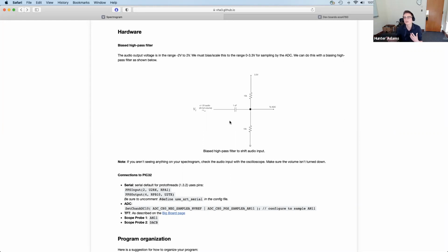So this is going to attenuate out signals beneath 16 hertz and it will pass signals above 16 hertz. Why is that a cutoff frequency that makes some sense for the lab that we're doing? You can't really hear stuff beneath 16 hertz. So if you can't hear it, it's an appropriate place to do a cutoff, right? So it's going to cut off DC stuff, and it's going to cut off all signals below 16 hertz, and it'll pass the other ones and bias them up by 1.65.